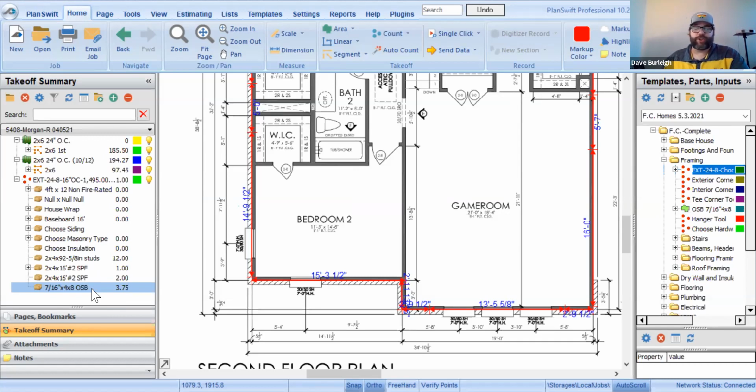So even there, cutting 2 studs per exterior corner, and you're going to have 12 to 20 exterior corners on a home. We're talking 24 to 40 studs that we've just removed just by not paying attention to the nomenclature, but understanding what actually makes that corner happen and what material do I need to achieve that corner.